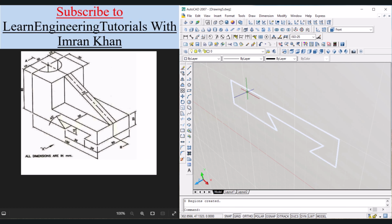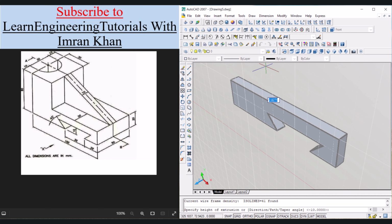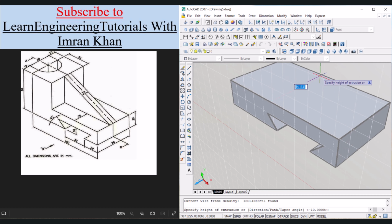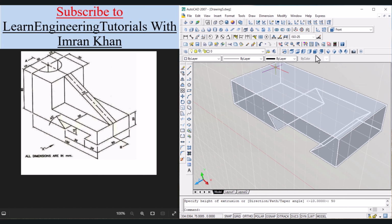Now we have to use region command, so REG, enter. Select all these objects, 8 found, press enter, and we can see a paper shape has been given to the wireframe. Now click on this object, click on extrude. Now in this direction we have to give the value of 50. Enter. Visualize this object in the front view.